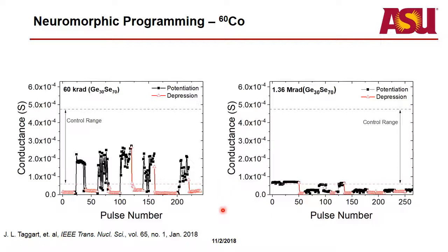And so like I stated before, for doing the DC sweeps, if we're seeing these kind of effects where you essentially have a dissolution of the filament, there's a time lag between when the pulse is applied and when the read bias is applied. So if we try to program this filament, it starts to partially dissolve. It's already in some higher resistance state than what it started initially by the time you apply the read. And so there might be some randomness, some variation in that. So sometimes you might capture it when it's in a lower state or when it's more dissolved.